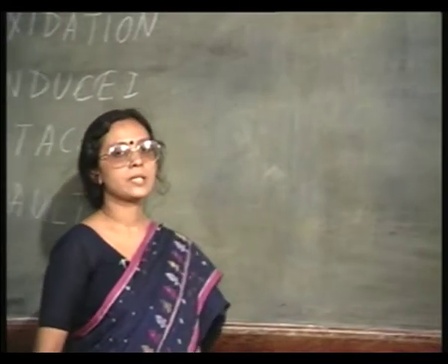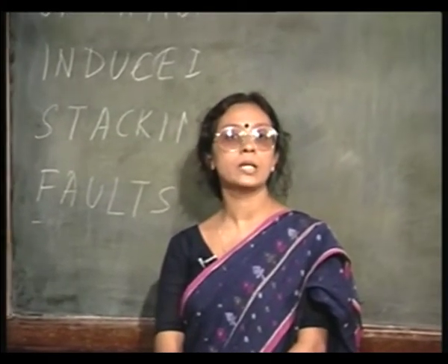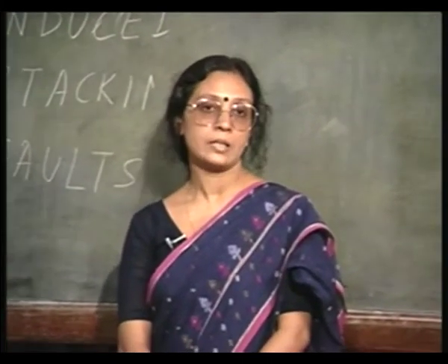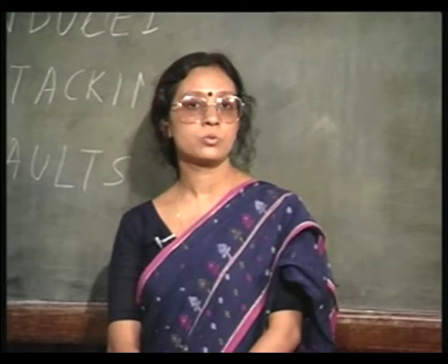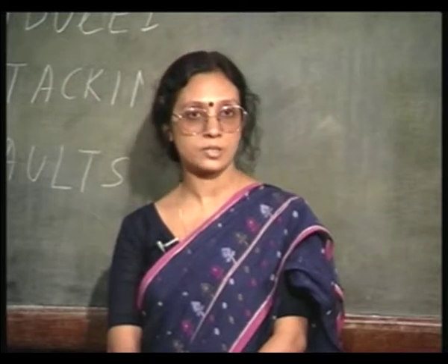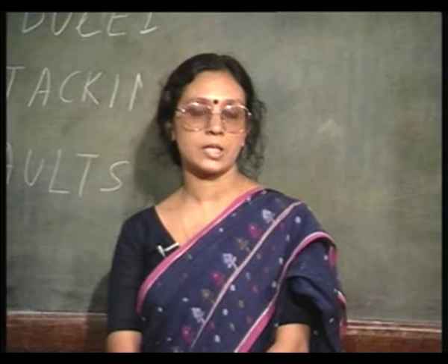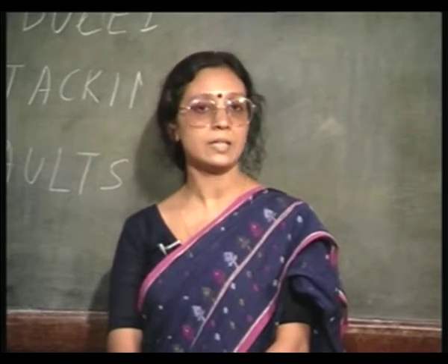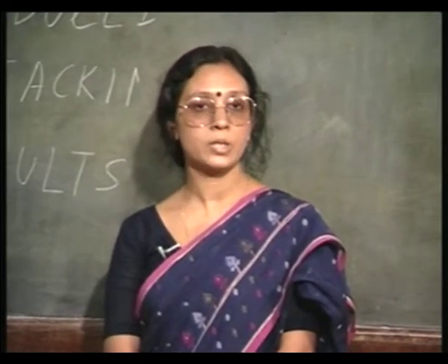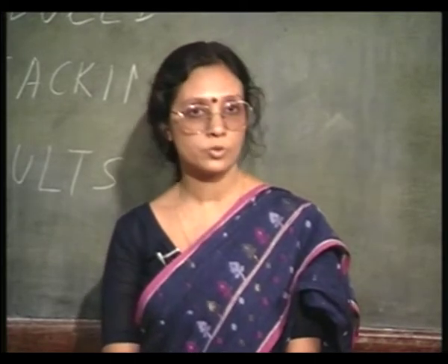In addition to measuring the oxide thickness, the capacitance technique can be used to evaluate the quality of the oxide film. That is, it can be used to measure the different charges that are present in the oxide, namely the fixed oxide charge, the oxide trap charge, the mobile ionic charge, and the interface state density. By doing different CV measurement techniques, it is also possible to measure them.